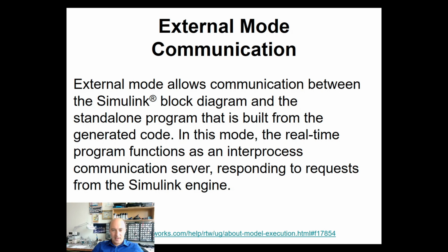So the external mode allows us to communicate between the Simulink block diagram and the standalone program. And the standalone program is what we will have as our model. Now it looks really complicated, but fortunately it is not, because there are only a few commands that you need to run in Simulink to do this.